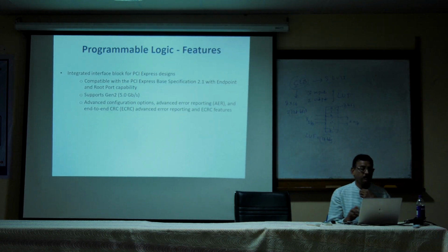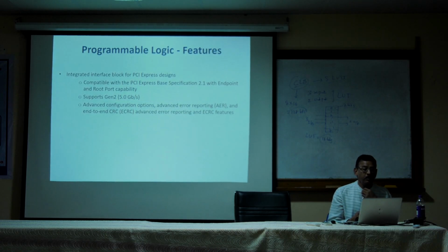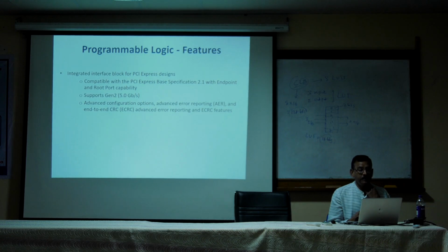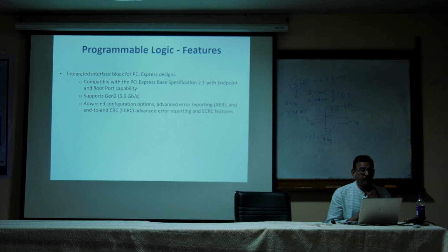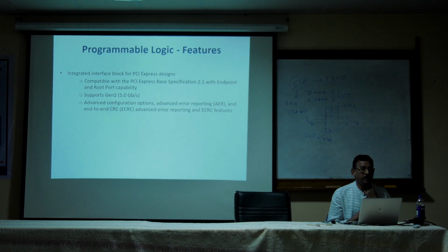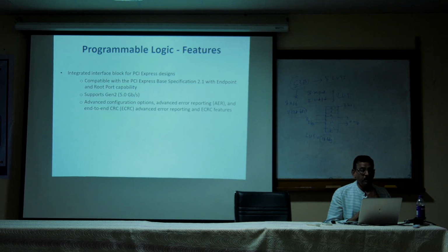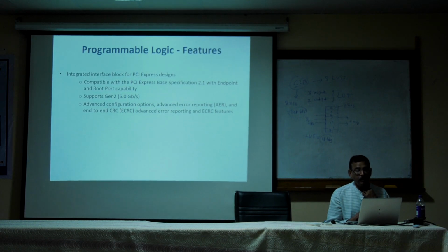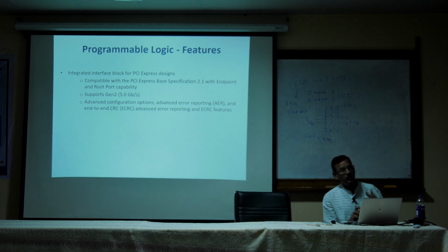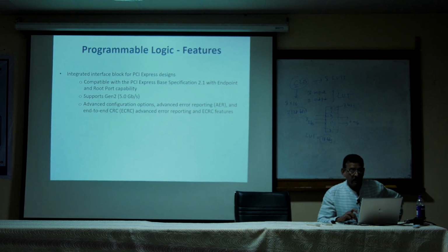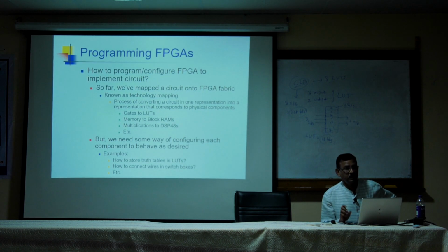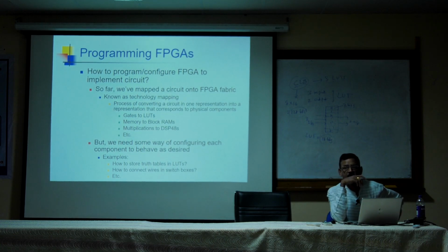It is compatible with PCI Express base specifications and supports generation 2, 5 gigabits per second. Advanced configuration options, advanced error reporting and end-to-end CRC, advanced error reporting and ECRC features. These are important features for this FPGA fabric, the Zynq 7000 FPGA.